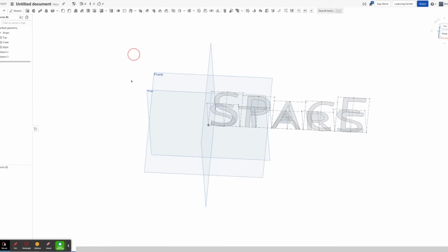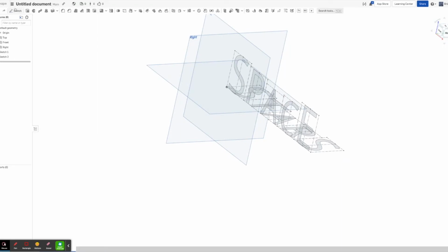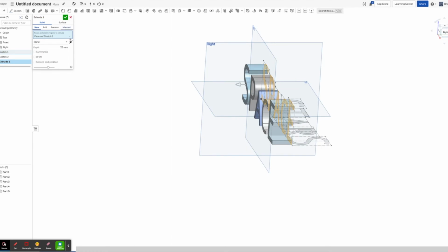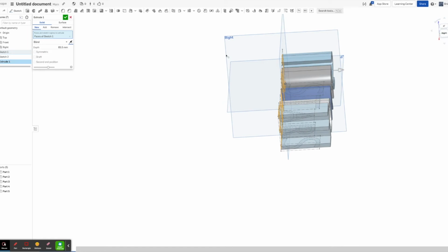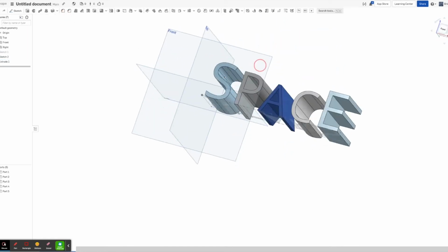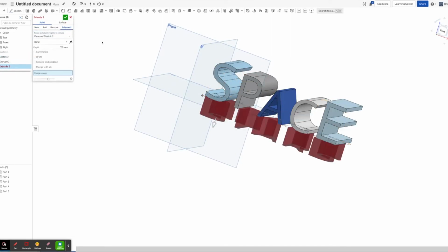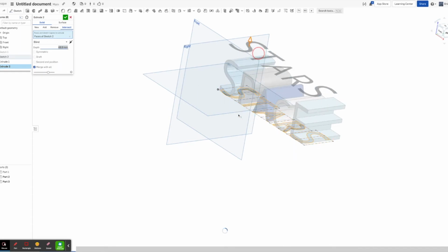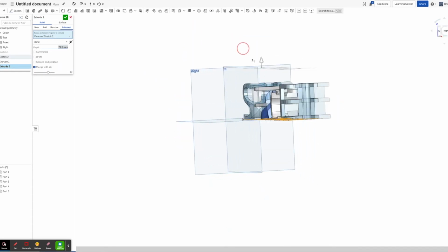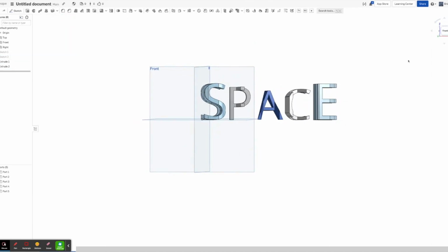And there you go. So now that I've made these two sketches, I can make the intersect extrusions. So I'm going to go ahead and first make an extrusion like so, a simple extrusion with the first sketch. And then I'll take the second sketch and make an intersect extrusion. And I'll make sure to merge with all. Make sure that the extrusion is going up. And once I've done that, I get this pretty interesting shape.